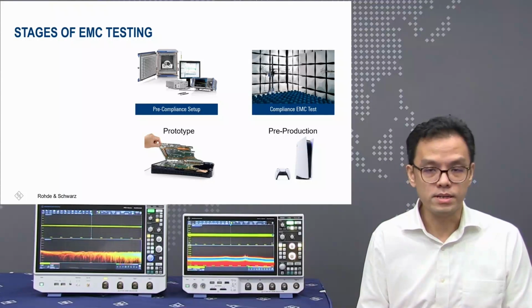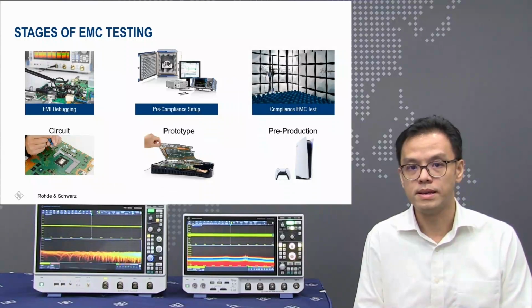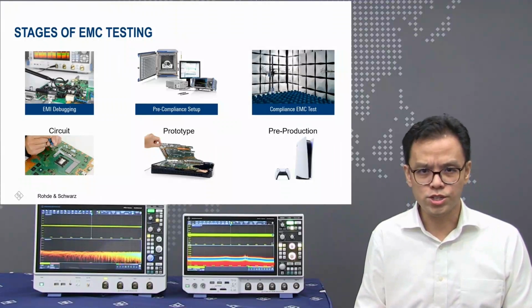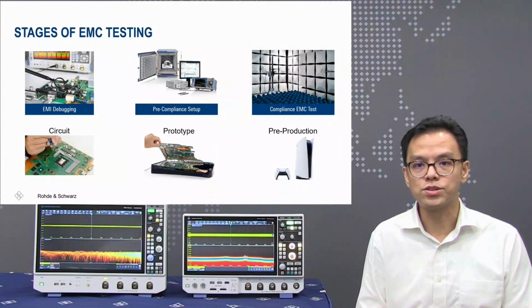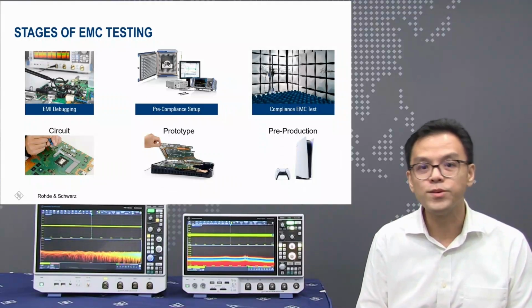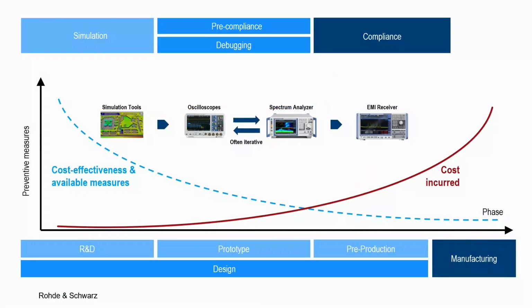Moving one step further, EMI debugging is becoming more and more common, especially for power-related circuits. Solutions to resolve EMI issues often involve the addition of capacitors and chokes, which occupy PCB real estates. Hence, it's advantageous to address these issues during the early design phases.